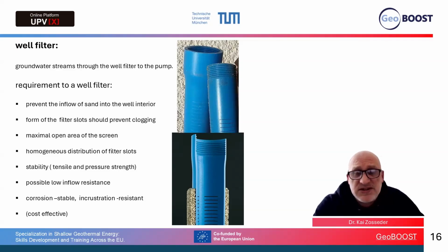The stability plays a role. If you have large filter slots, maybe the stability of your pipe is not so good. So you have to design that quite well, but normally it's standardized anyway. So these are some requirements for the well filter.